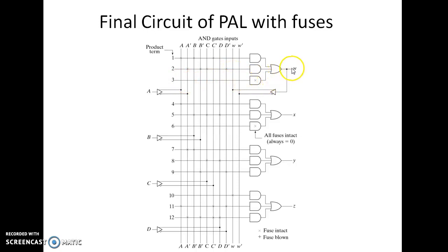There are only two product terms for W. So that's why we can eliminate this AND gate by simplifying the functions using K-maps. This is an advantage of simplification. Right? You can also realize from the direct functions, but there are disadvantages. You require more number of AND gates. So to reduce the number of AND gates, we are simplifying using K-maps.